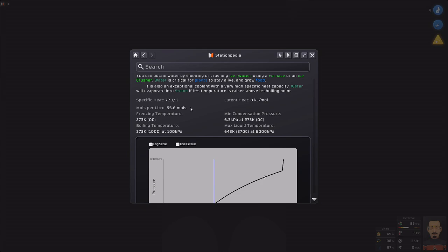Now, this is a very extreme example, I'm just going to say. And so then, however much of your latent heat was spent to cool down your evap chamber, now we have this extra going down. So divide it by 10, divided by 72. That means I go down an extra 10 degrees. So I went from 25 to 10 degrees. Well, now, whatever is attached to it has to heat exchange. So if whatever was attached to it was a gas, 25 Celsius, you know, we're gonna equalize some temperatures. So a whole lot of thermal energy will have to go back into the water to get it back up there.